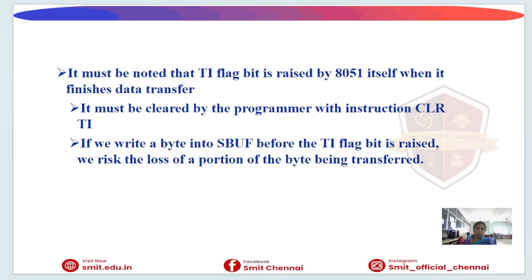The TI flag is automatically set by the hardware when transmission completes. However, the programmer must clear it manually using software. This is done using the instruction CLR TI. This is the CLR TI.